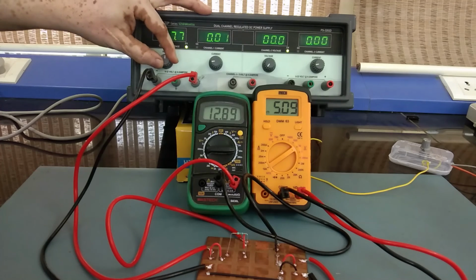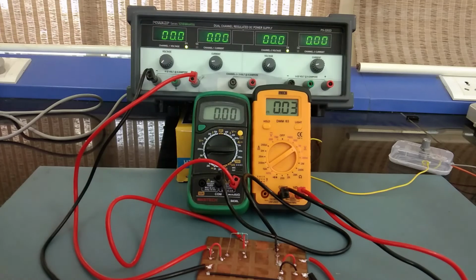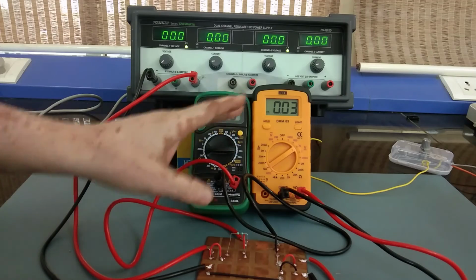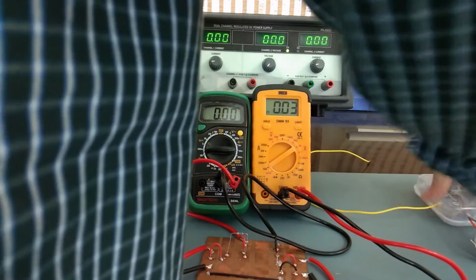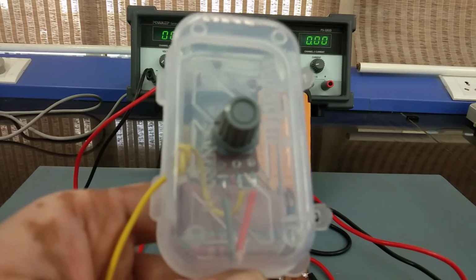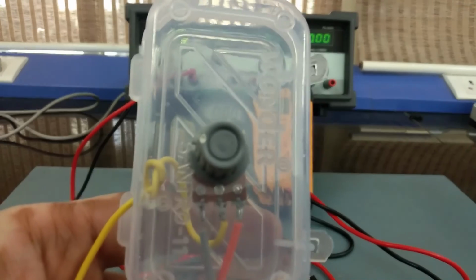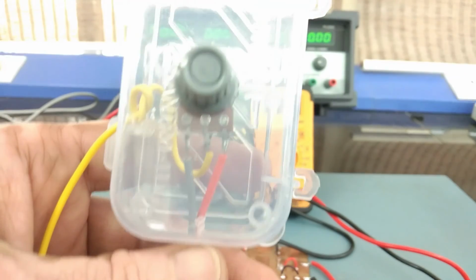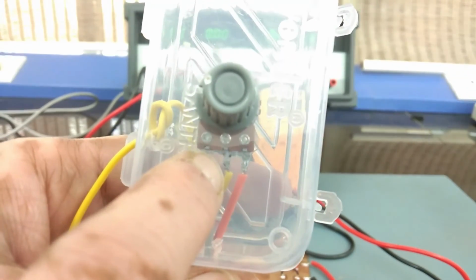Okay, so now what we will do, we will see the line and load behavior of Zener as a regulator. For that we do not need this ammeter, okay, but still we will keep it there on the circuit. We will retain it in the circuit, and as a load I will be connecting this arrangement. You can see here this is simply a potentiometer. Alright, and we will be using two terminals, the center terminal, that is the wiper terminal, and one of the end terminals for this purpose. So I will be connecting it across the Zener.